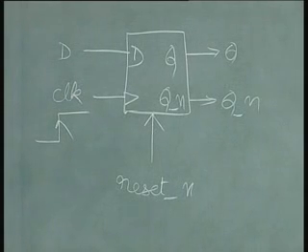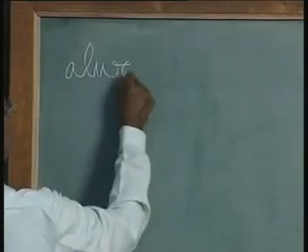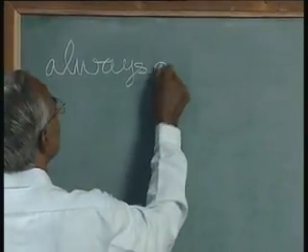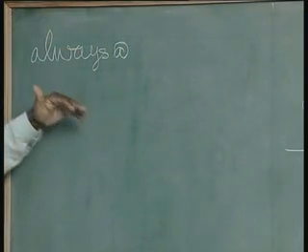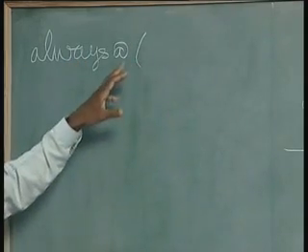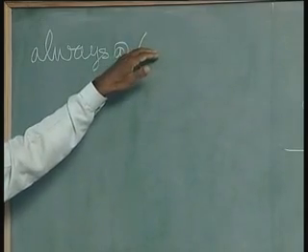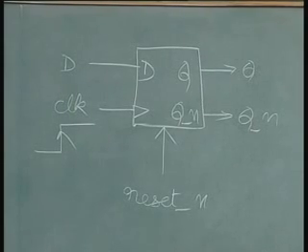And now it's very easy to code this. First we'll reuse the same always block, but the connotation is different here, because this is a sequential circuit. We'll use always at. This portion is common to combinational as well as sequential, but here makes the difference. Within brackets, the same inputs come into picture, but this time it is going to be a clock rather than the ordinary logic signals. So that makes the difference.